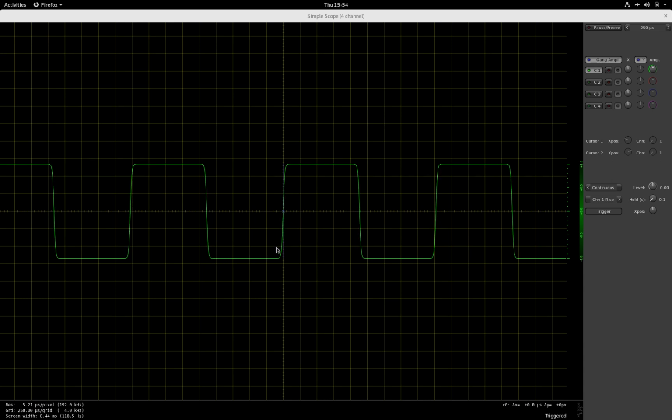So the negative half wave will look the same as the positive half wave. It will be as wide, and it will also be as high as the other. The signal is basically point symmetric through the origin. If we feed a sine wave into it, which is also point symmetric through the origin, it will remain soft clipped, so the edges of the output waveform will be rounded and smooth.